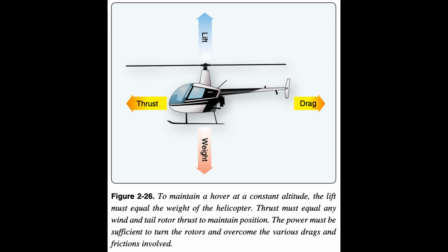During hovering flight, a helicopter maintains a constant position over a selected point, usually a few feet above the ground. The ability of the helicopter to hover comes from both the lift component, which is the force developed by the main rotors to overcome gravity and aircraft weight, and the thrust component, which acts horizontally to accelerate or decelerate the helicopter in the desired direction.